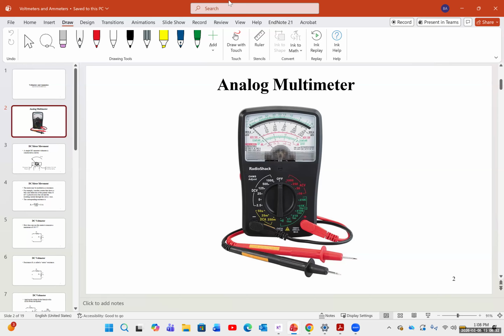Today, I brought with me an analog multimeter. I want to show it so you can all see it. So this is an example of an analog meter that you would see. And you can see, even when I wobble it, the needle is moving. So imagine what happens if I throw it down, or put it on a shock or put a magnetic field on it. It's going to create problems.